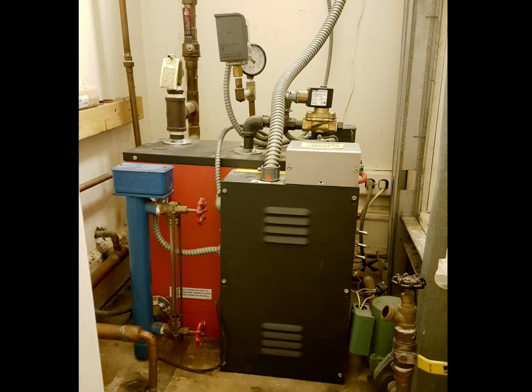If I was going to be responsible for heating up two 73-unit apartment buildings apiece, then you better believe I was going to be warm as well, considering the fact that my apartment had not a single radiator inside of it. And of course, the more steam pressure you have, the hotter your radiators get. That's pretty much the only reason why I ran it at that pressure level. Now, I could have run this thing at 2 psi and it would have run just fine. But I ran it at about 7.5 to 8 psi.